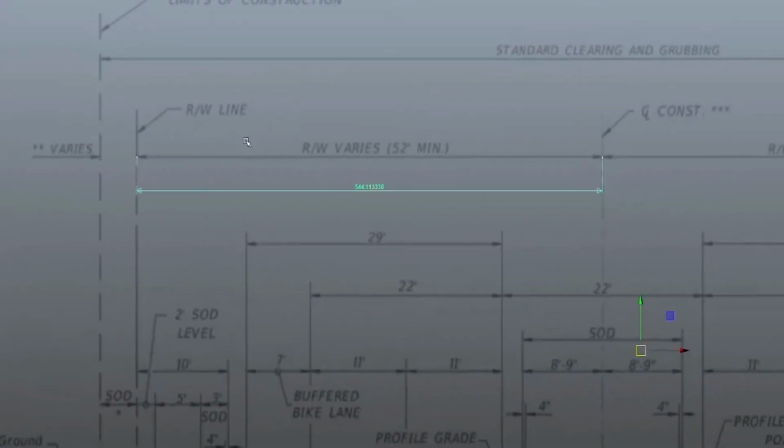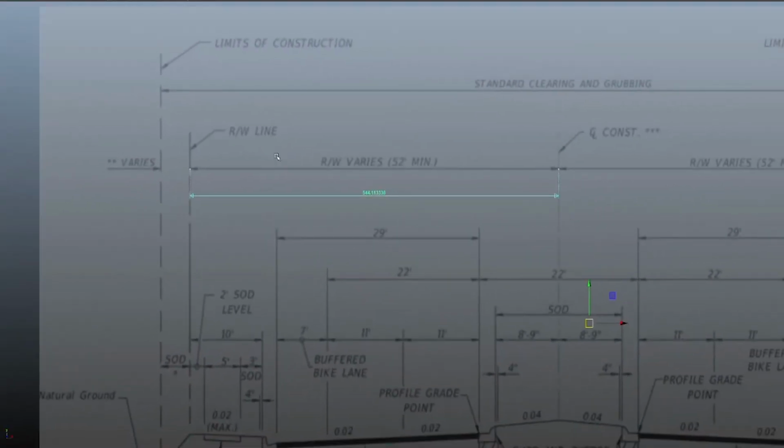So let's scale this down so it's 1-to-1 and matches the design plan. With my measure tools selected, I shift click the image plane and then group it. So I'm grouping all these three things together. So when I scale it, now it's going to scale everything together.